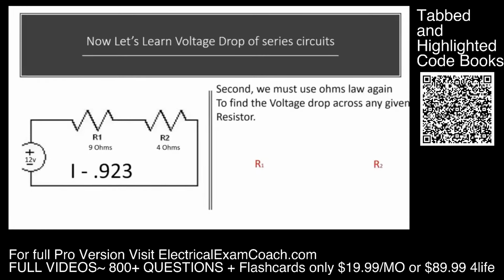Second, we must use Ohm's law again to find the voltage drop across any given resistor. The voltage drop is going to be equal to R1 multiplied by I, and the voltage drop of resistor 2 is going to be equal to that resistor multiplied by I. Because remember, we're just trying to find the voltage drop. So E equals IR. Just plug in the knowns. In this case, we know the I and we know the resistance, and we're looking for the voltage drop. So we just multiply those two together.